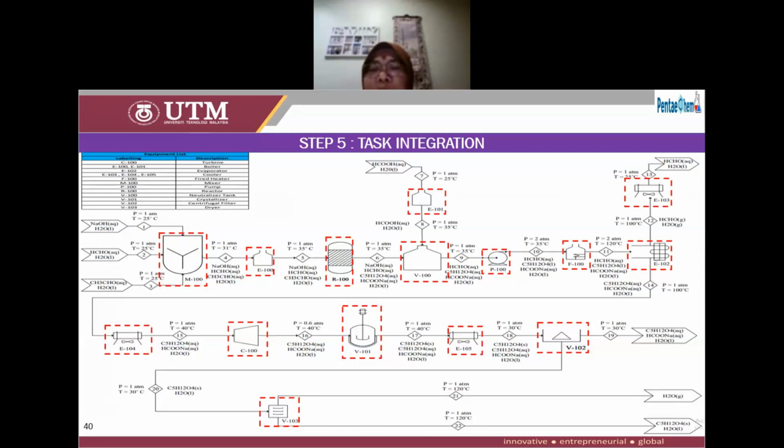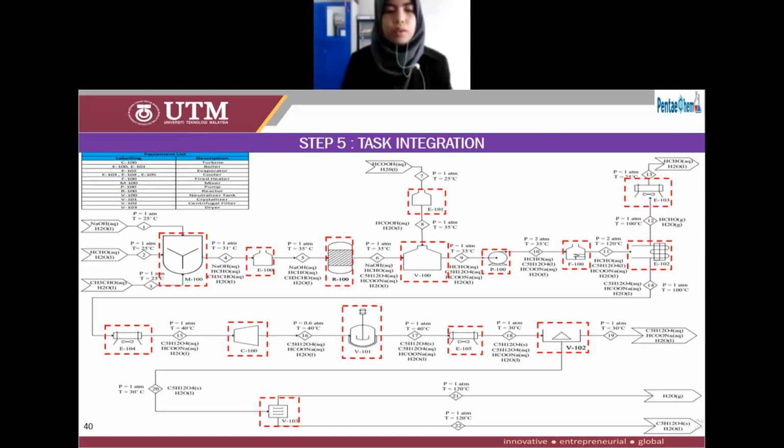You must reduce the temperature to 30 degree C. That is my question. Because the centrifugal filter's working principle is that it will spin, and when it is spinning it will generate heat. Due to the high speed, there will be a high temperature. That's why we want to use operating condition as low as possible to avoid overheating.